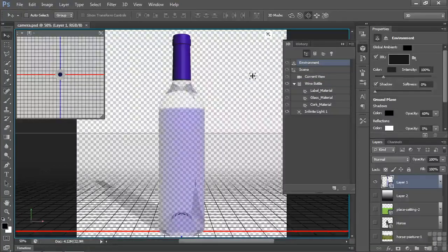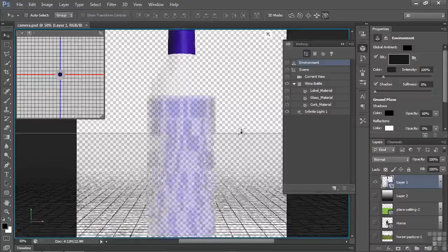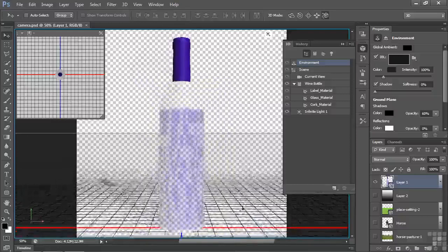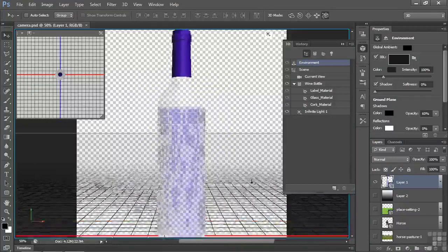Now I've got 5 camera control tools, which are the same kind of control tools when you control a 3D object. And they're right up here. I'm going to talk about them here right to left. Some of the names are confusing, but you'll see how they work in a moment. If I click on this first one, that's scale. Take a look at it. You can see that it gets smaller and larger. If I use scale, that means I'm moving the ground plane closer or farther from the viewer. So right now, if I go down here and start dragging, if I drag up, it drags the ground plane closer to you. If I drag down, it moves the ground plane farther away. I can't make it go left or right, just closer or farther.